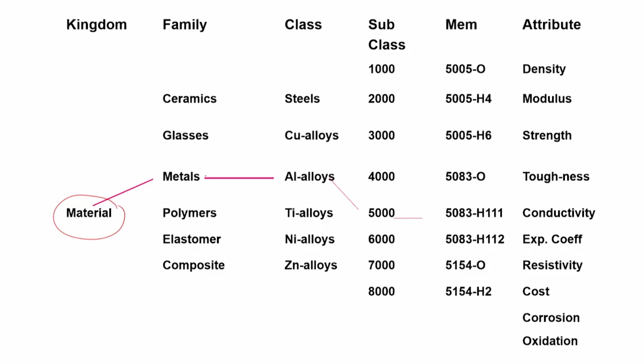things will keep the metals and the composites as two candidates, but composites till today, other than in aircraft, application of composite for automobile is very expensive. So, except certain parts of a racing car, we normally do not go for the composites. So, we will keep ourselves in the metallic domain, and as we are looking for a lighter density, lighter automobile, out of all the possibilities of the classes of metals, we would be ready to take aluminum alloys.